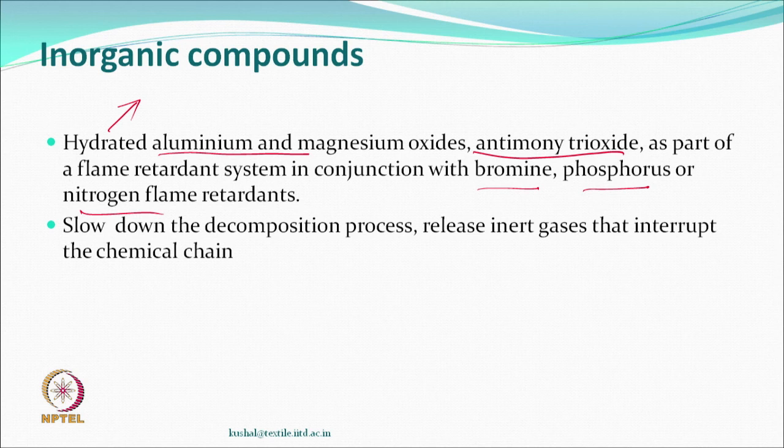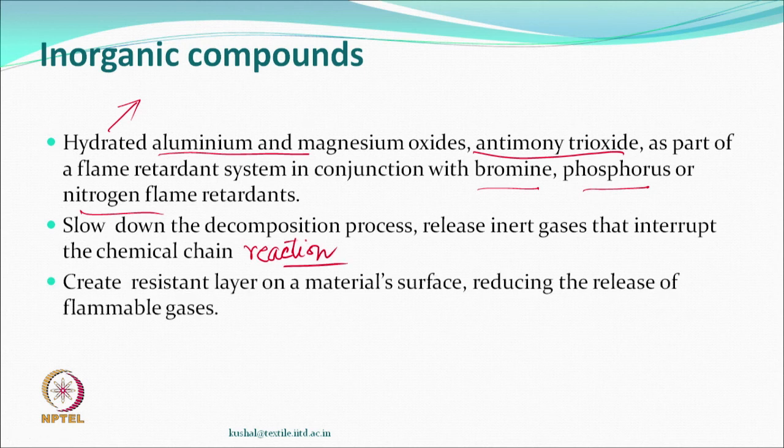Of course, they will do exactly the same thing, which is slow down the decomposition process, release of inert gases that can interrupt the chain reaction, the chemical chain reaction, which is the free radical reactions also. They can also help in creating a layer, a flame resistant layer, and reducing the release of the flammable gases.